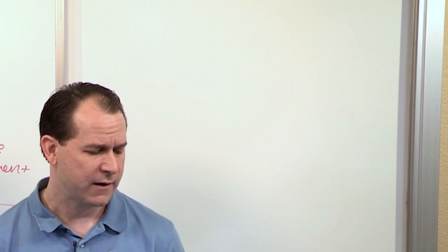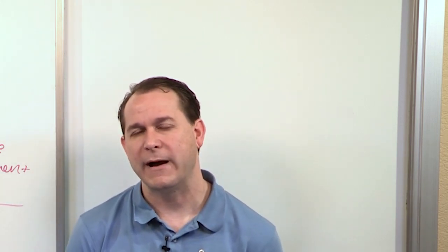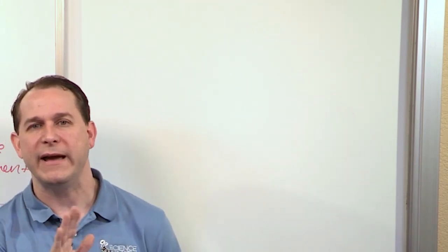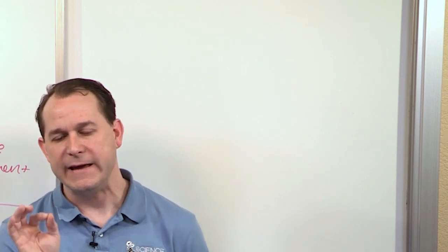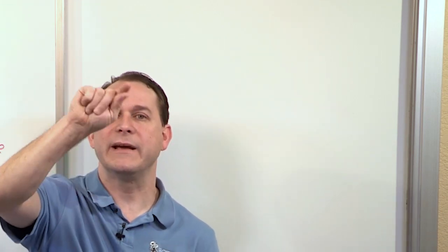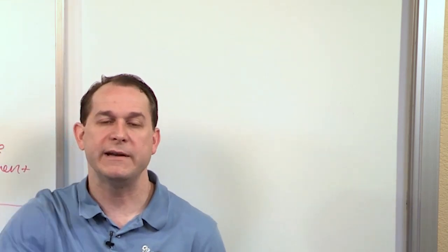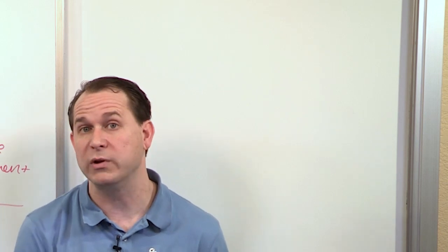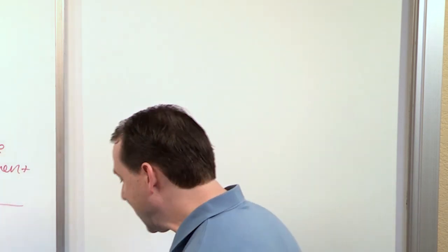Resistors are easy, right? Because, well, what do we talk about? Resistors don't alter the phase angle between current and voltage. If you have resistors in the box, if the voltage goes up, then the current's going up in lockstep with it in terms of a cosine. They both track each other up and down if you have resistors only in the box. So let's look at that case and see what we can learn from it.